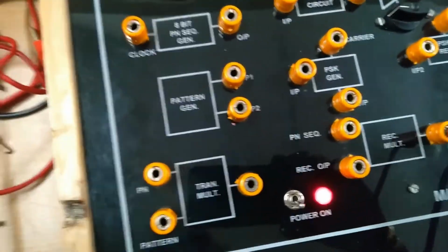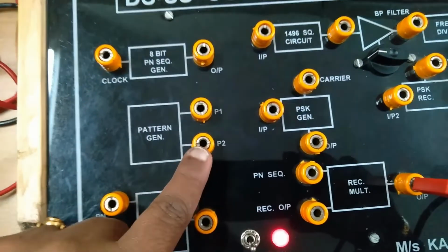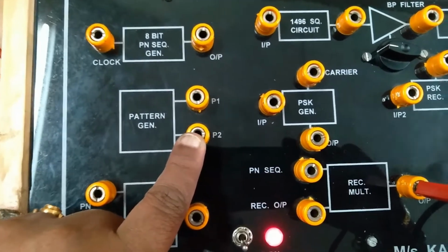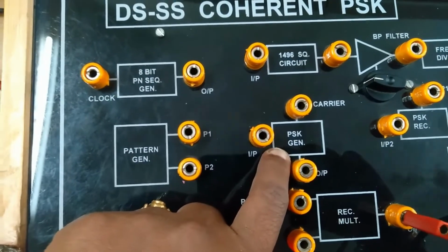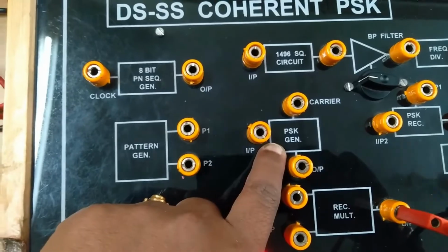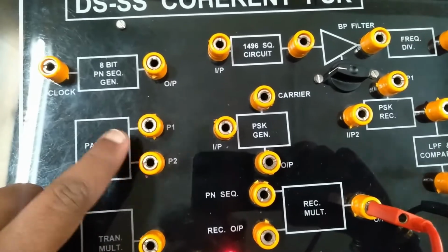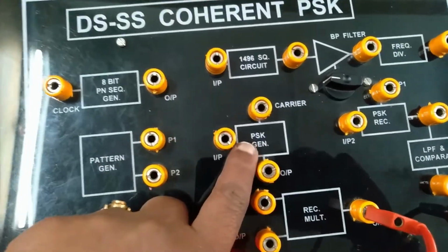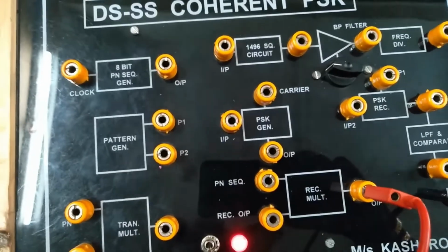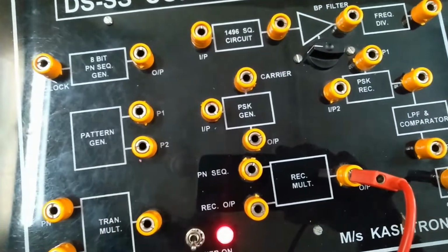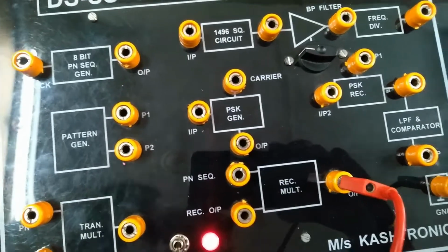Spread spectrum is, see, if I directly multiply only the bit pattern by the carrier, for example, my bit pattern is of frequency 1k. If you go through the frequency spectrum of PSK, you'll see that the center frequency is Fc, and the lobes created on both ends are at Fc plus Fb and Fc minus Fb. Fb is the 1k frequency. Fc, for example, is 20k. So 20k plus 1k, that is 21k on the positive side, and 20k minus 1k, that is 19k on the other side. The difference is the spectrum occupied for transmitting the modulated digital data.